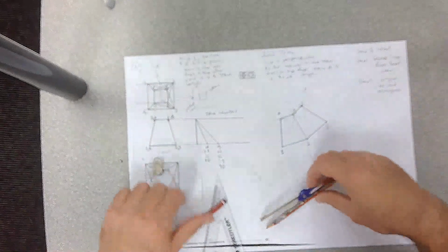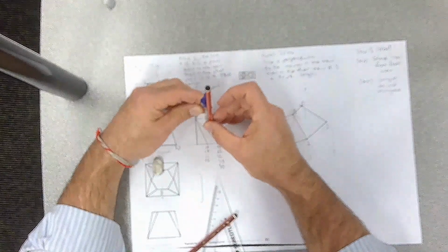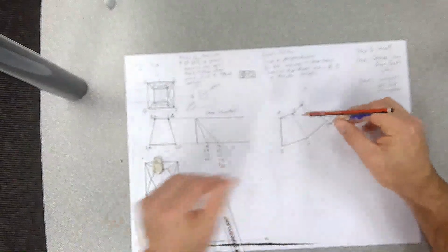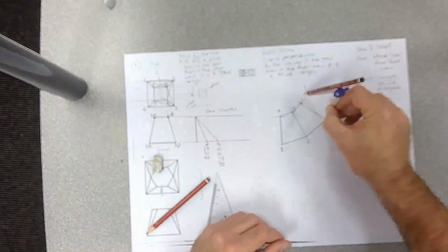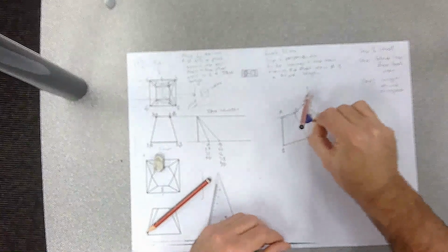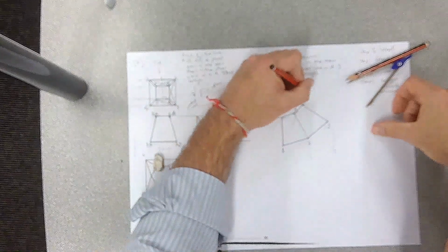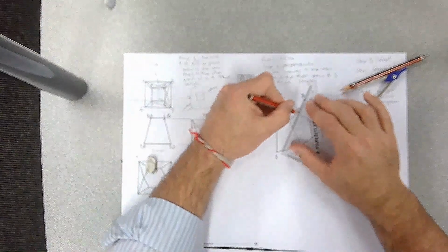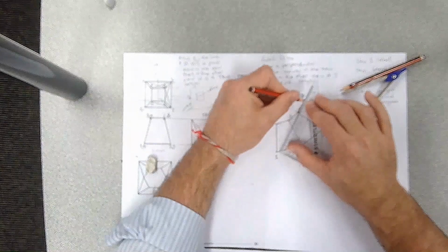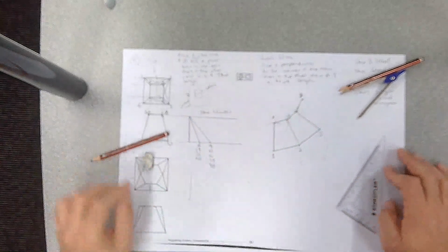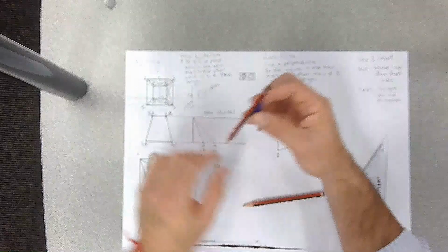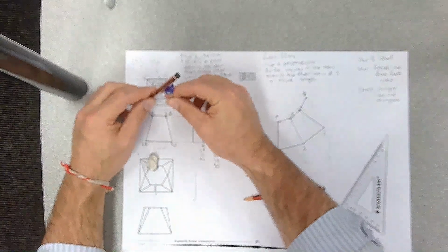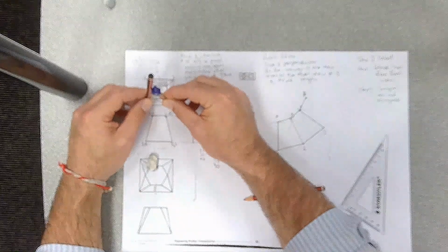So what I need to do is grab my length off my true lengths graph, sit my compass on 3, swing my arc, and that's my point D. And then we need to go from 3 to 4. Now we know 3, 4 is a true length because it's perpendicular to the viewer in both of them, in fact. So we can go off the top.